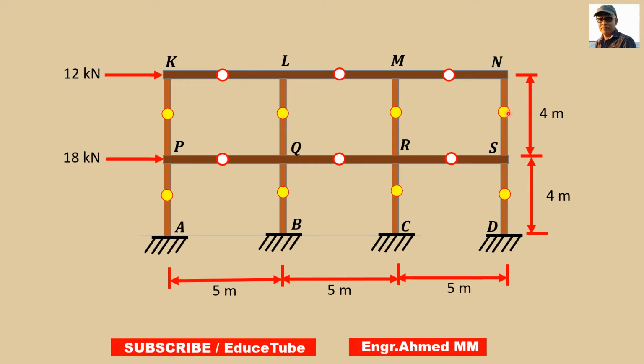Third assumption: at a given floor level, say this floor, the shear at the interior columns, I mean here and here, is twice that at the exterior column hinges. So how is it?